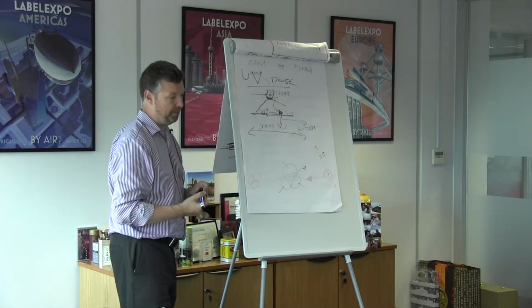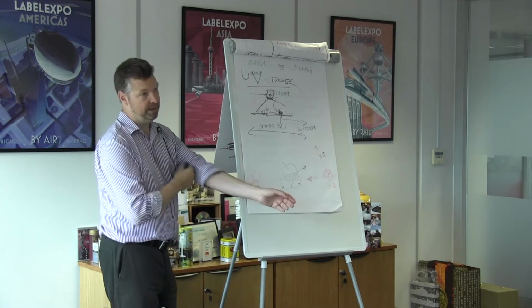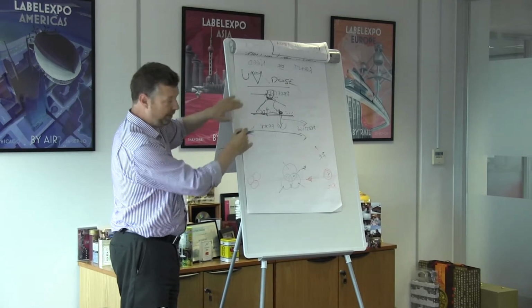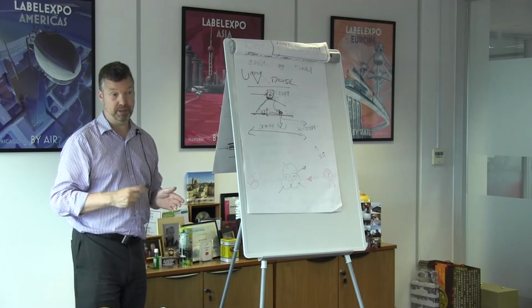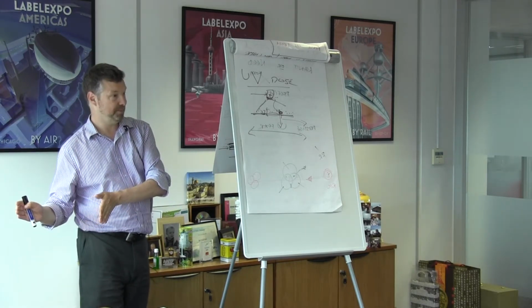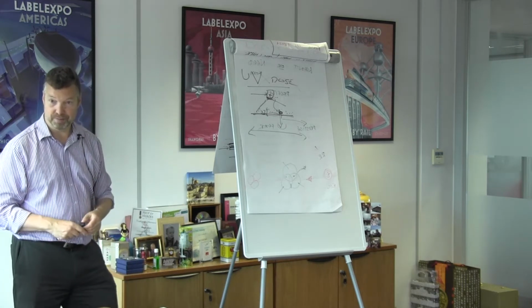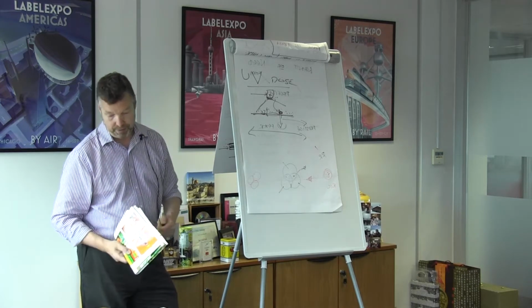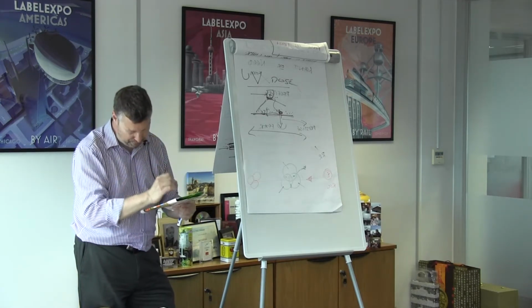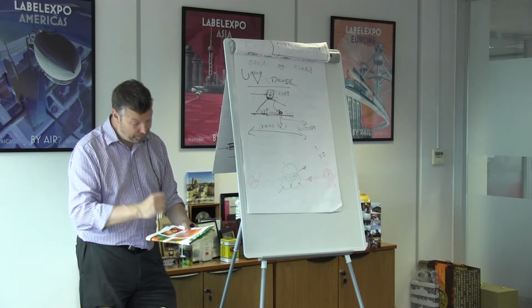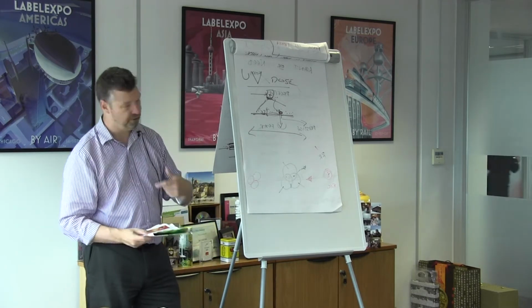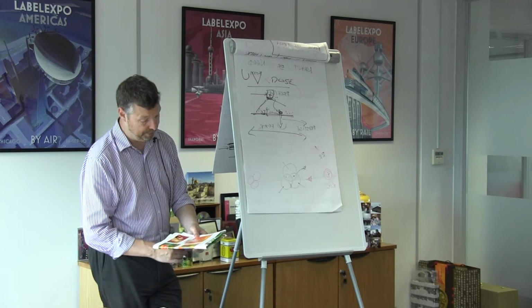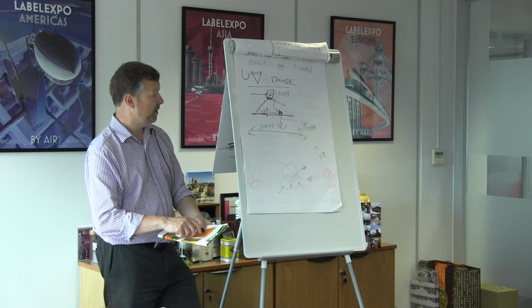You might have heard about offline testing. So what's offline testing? All this is happening on the press, or on the rewinder. You'll also see when you go to a label plant a little laboratory, with people in white coats. What they're doing is running quality control tests on the finished label. They'll be doing the same kind of thing: getting a spectrophotometer and measuring the colour, looking at the image to make sure there's no pinholing, just doing a final check on random samples of the label.